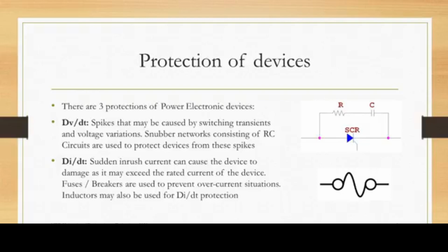Due to the arc, the impedance of the fuse is increased, thereby reducing the current. However, an arc voltage is formed across the fuse. The generated heat vaporizes the fuse element, resulting in an increased arc length and further reduction of the current.